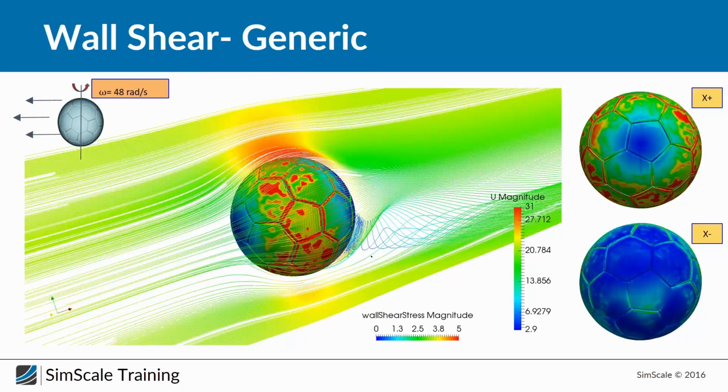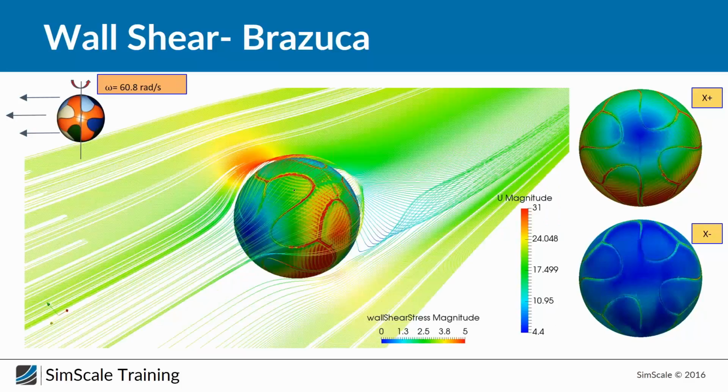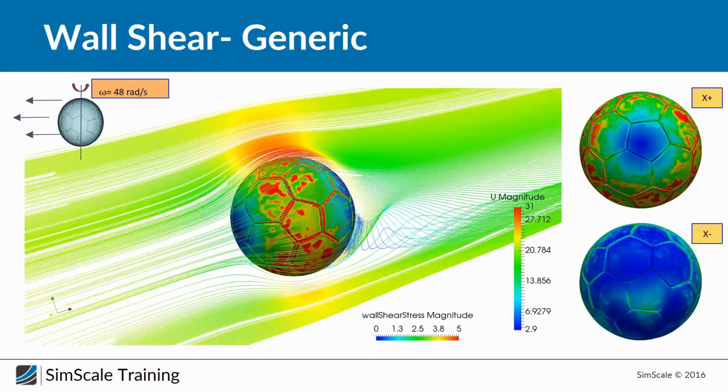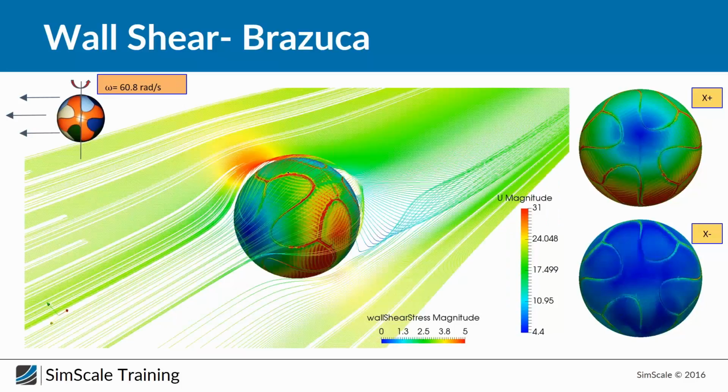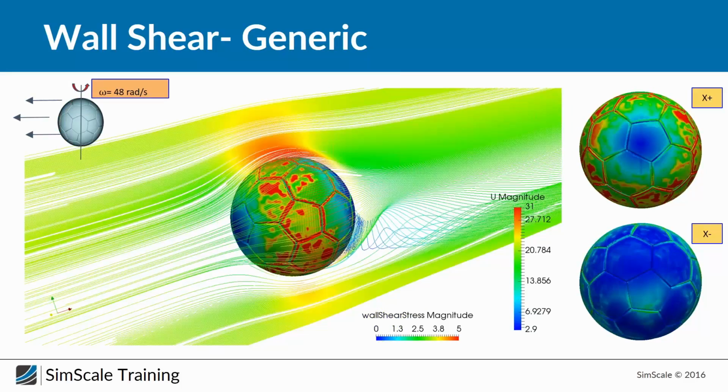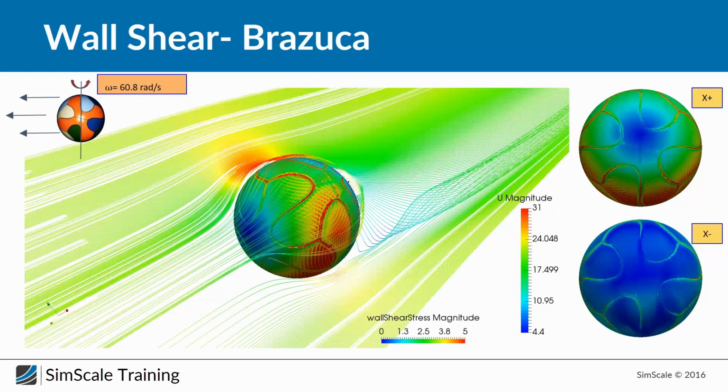We have another structure, and this is related to the path of the seams, because basically what you can see is the wall shear stress is increasing massively in the area where it's stitched or seamed. And so this is, in the end, a reason why the flow is separating, and this different structure is much more optimized and results in later flow separation, which you can see here. Where it becomes blue, we have a flow separation, and here the blue area starts much later.